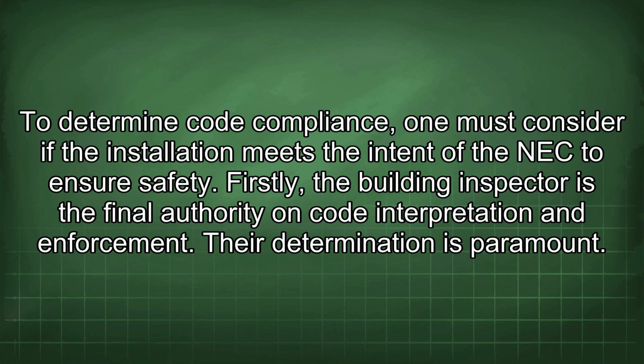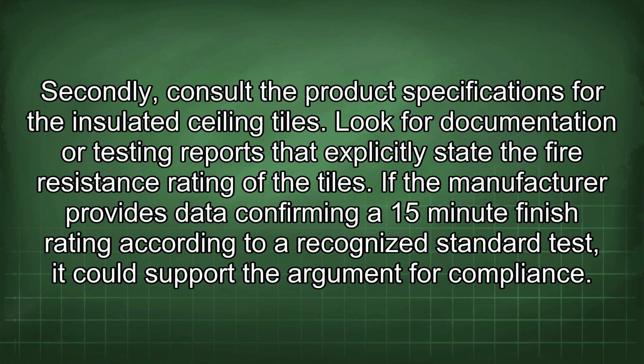Firstly, the building inspector is the final authority on code interpretation and enforcement. Their determination is paramount. Secondly, consult the product specifications for the insulated ceiling tiles. Look for documentation or testing reports that explicitly state the fire resistance rating of the tiles.